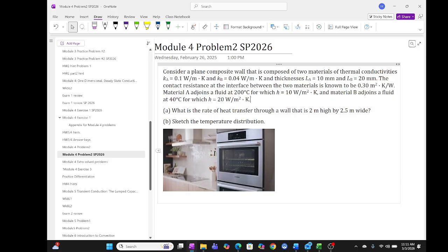Does this make sense? So what it means, you are trying to transfer the heat from this side to this side, equivalent to I going from here to here. If we have a resistance because of the air much higher than the solid, then this I or Q is going to diminish. The Q value is going to diminish, right? And that will be reflected by the change of temperature, or in current, change of voltage. So in heat transfer, as long as there is a temperature difference, it is going to flow, right?